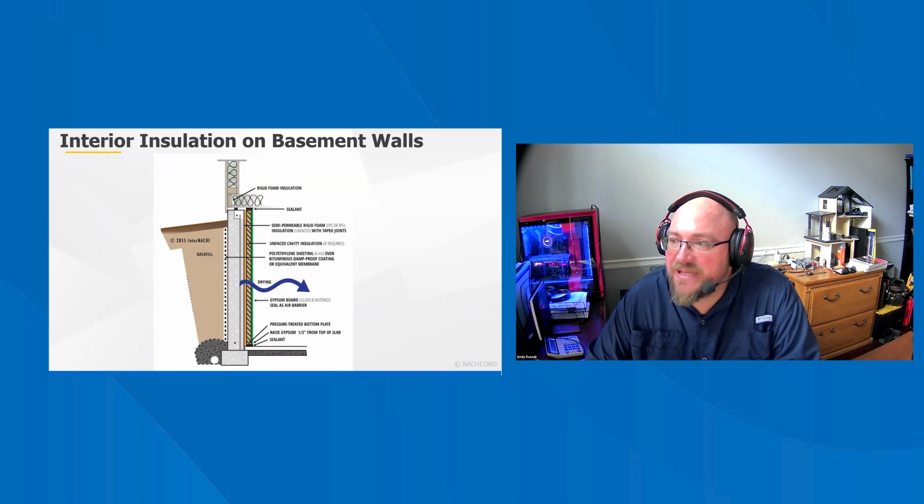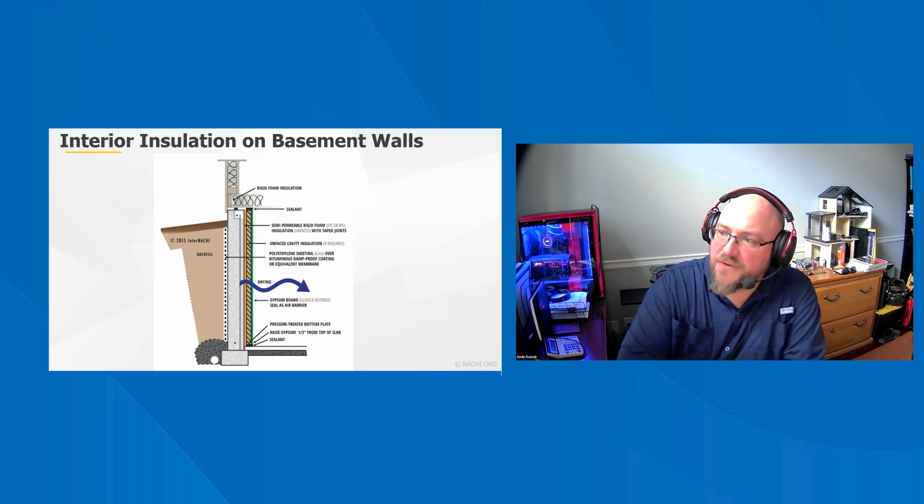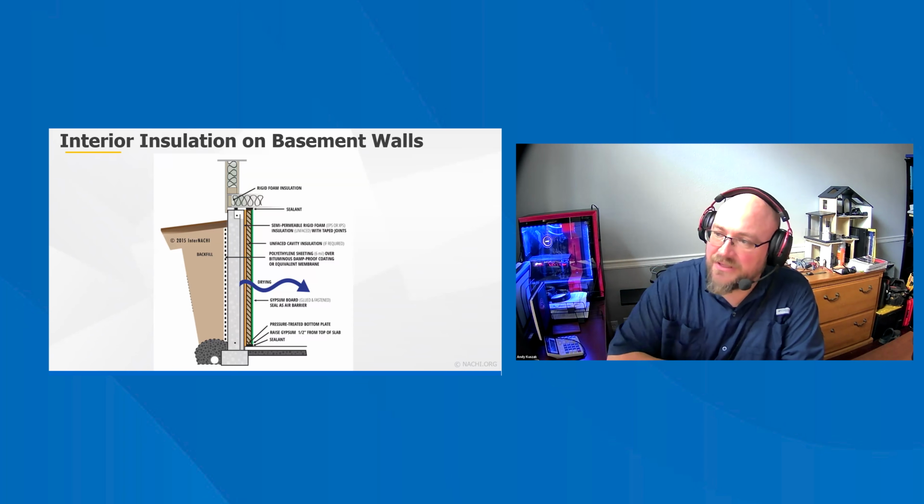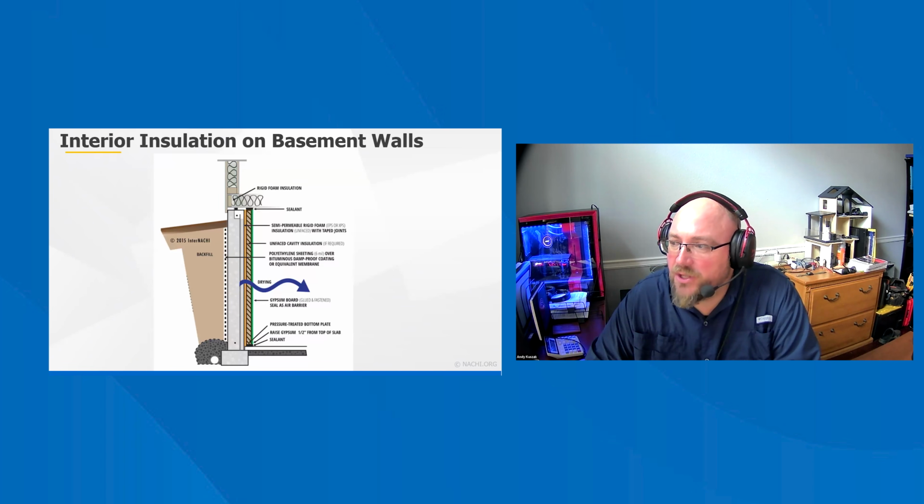The basement's finished walls need to be insulated to minimize cold surfaces. Cold surfaces, such as on the foundation wall, can create water condensation and raise humidity level in the basement. The concrete foundation walls are below grade and are therefore relatively cool to the touch, especially if finished walls are insulated. If the basement air, which tends to be warm and humid, particularly in the summertime, passes through the finished walls and comes into contact with cool foundation walls, condensation may form and cause moisture problems, including damage and mold growth. The rim band joist area, which is the area directly above the foundation wall, is of particular concern because that area tends to stay relatively cool all the time.